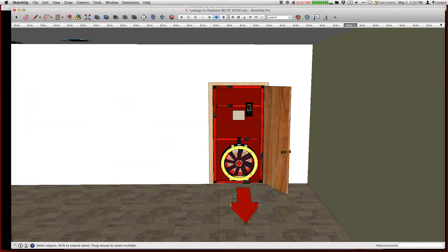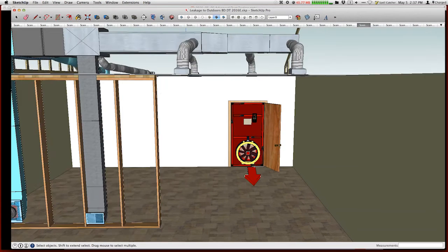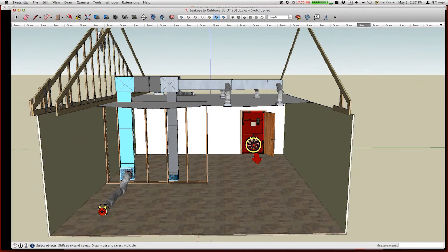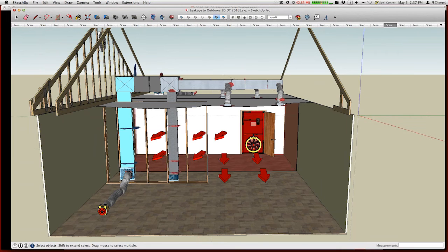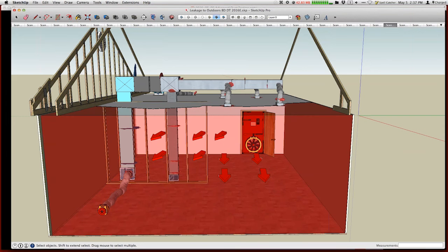So I have my duct set up, and what I normally would do, I could do a pressurization total leakage test. So this is my total leakage duct test all by itself, so I can do that and find out what my number is. And I want to focus on that leakage there, so now I can add a blower door. And so again, notice that the blower door and the duct test are doing the same concept. All right. So I'm pressurizing and pressurizing on both methods.